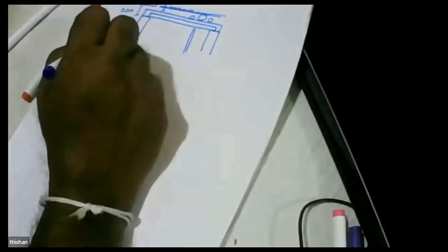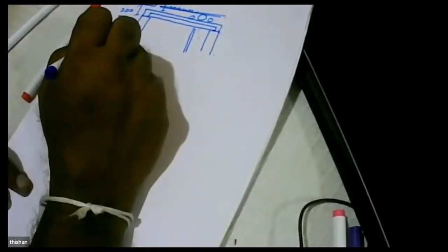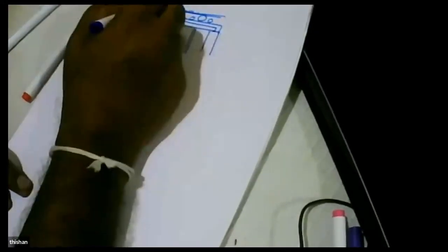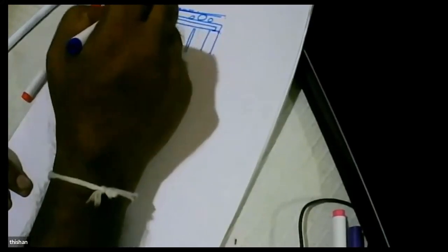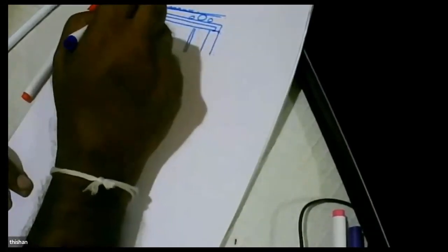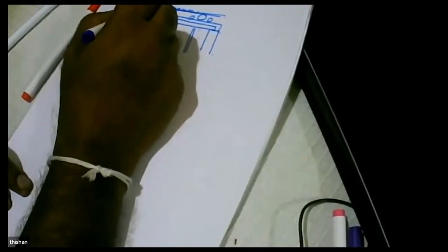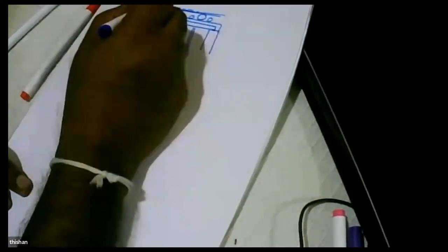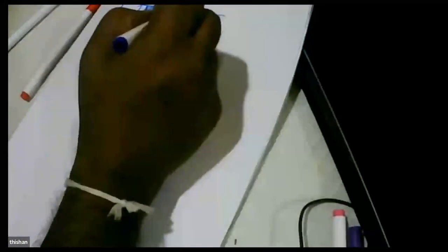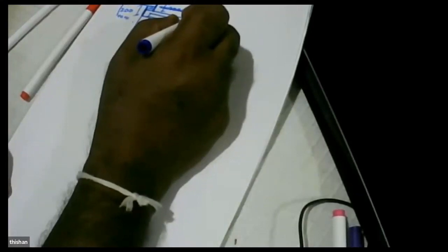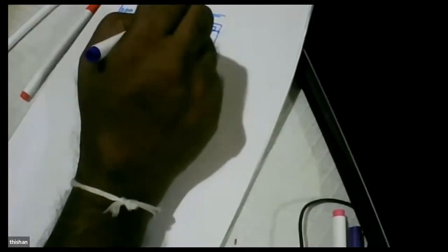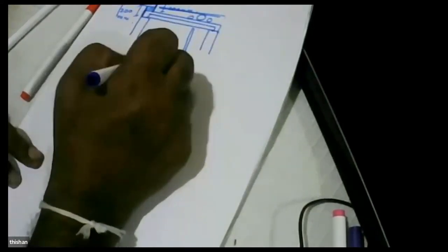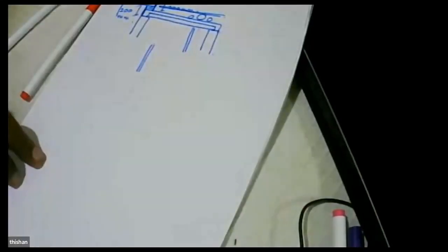Because this allows us to make a drop of 200 millimeters, here of course we have to fill it with concrete when you are doing the slabs. So what you do is you fix a timber plank, and because this slab is supported, we can fill the concrete when this concrete is done. So basically we can minimize the need for any horizontal chasers in the walls, because most of the plumbing work can be kept as vertical as possible.